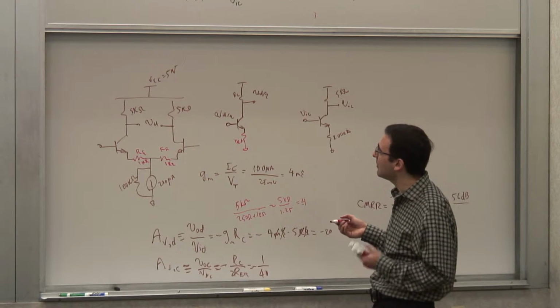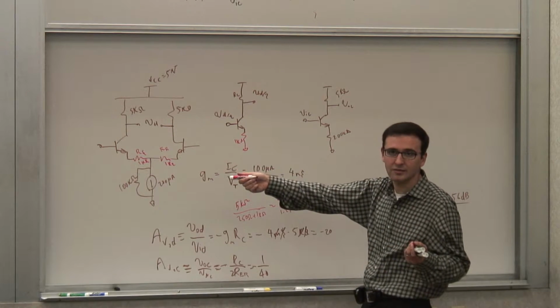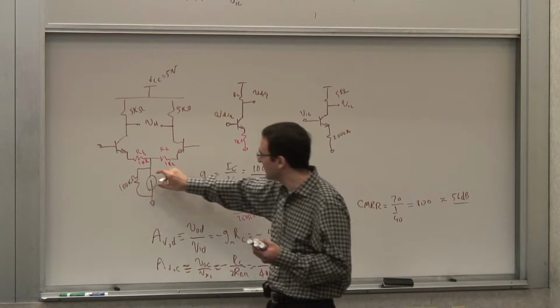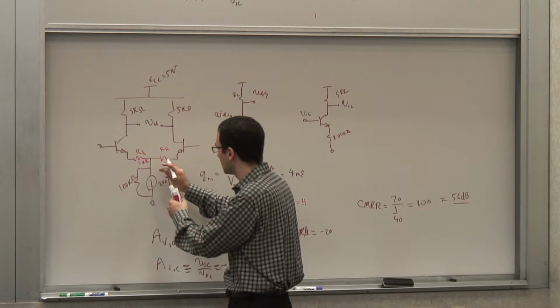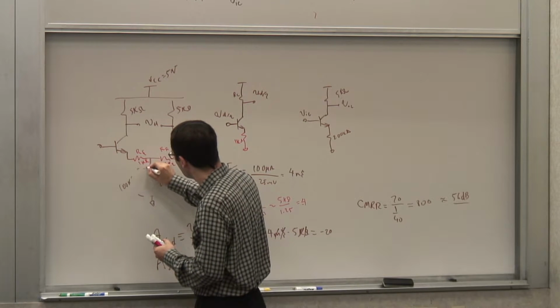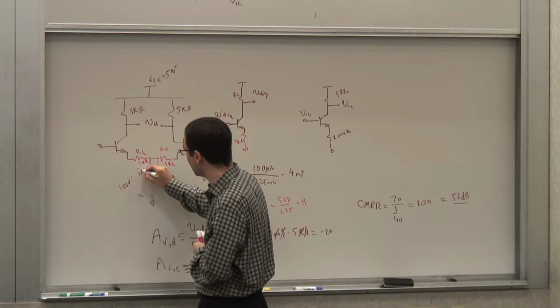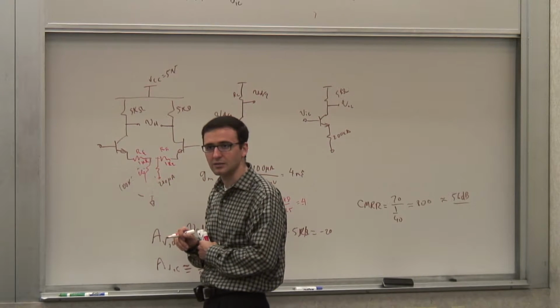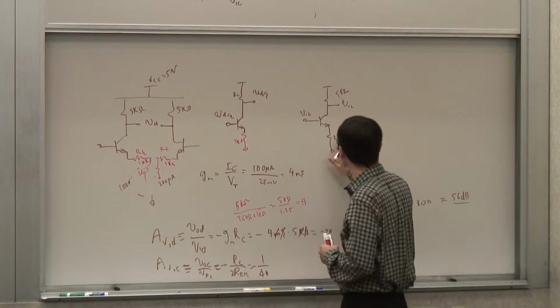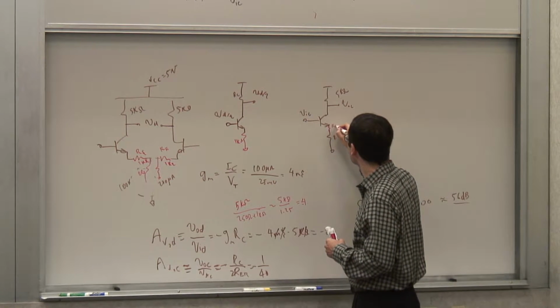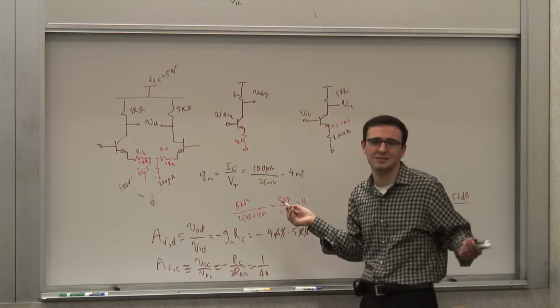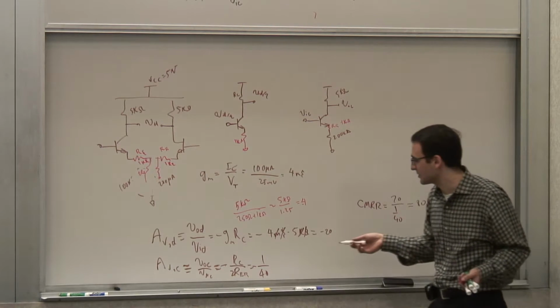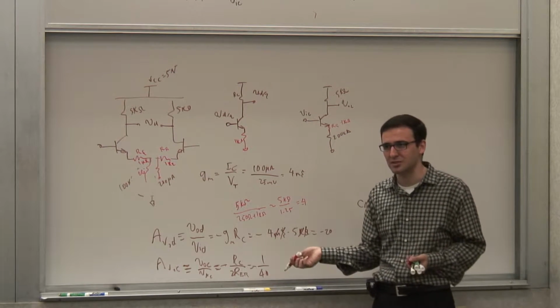Well, even in my common mode circuitry, I still have that 1K, right? Because when I split this into two equivalent 1K and 1K, it still will be hanging off of here. So if I look at it that way, it would be 2RE and 2RE, and I break it here. So what I would have is RE plus RE. So I have 1K here, but I already have 200 kilo ohms, so it's not a big deal. It makes it a little bit different, but it's pretty much the same thing.